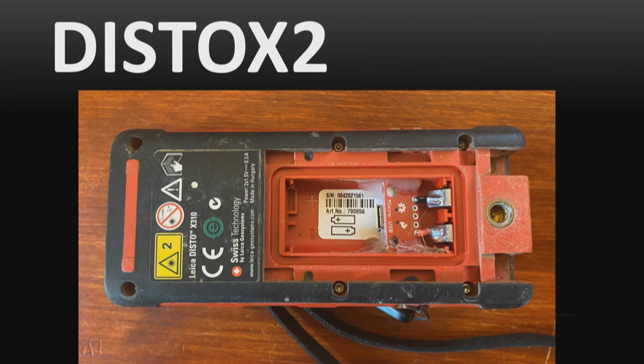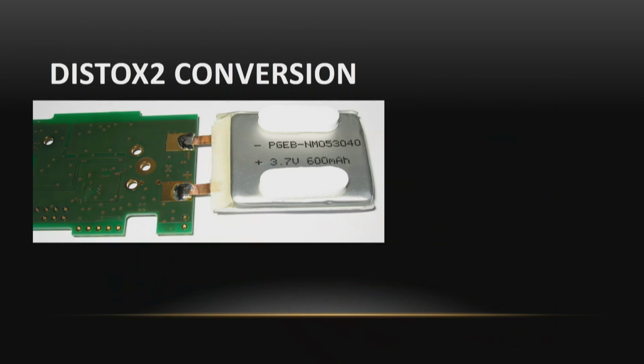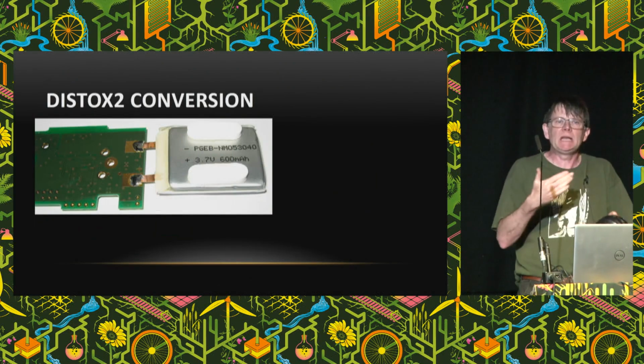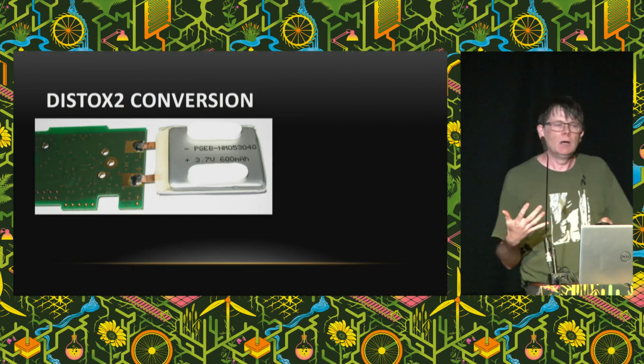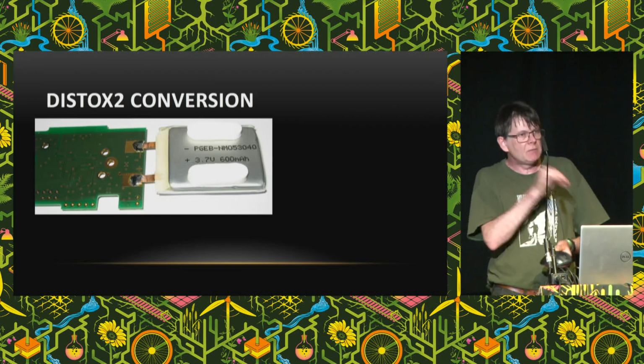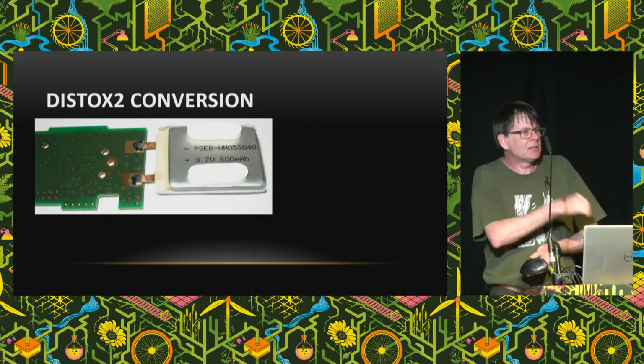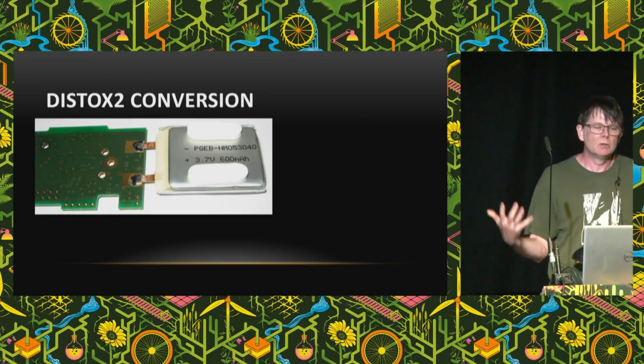This is some insight into the disto conversion. So the Disto X310 is the Leica device. We replaced the battery compartment with a USB charging lead. The original version actually tapped into some test pads on the PCB, and it scraped the data going to and from the LCD display to get the laser distance, because the really hard thing to build yourself is a laser measure. And so we used the off-the-shelf laser measure, scraped the data off the LCD test pads, and got those into a daughter board that went on.